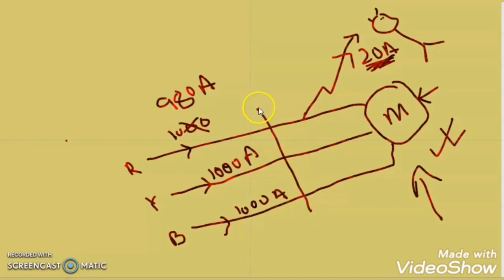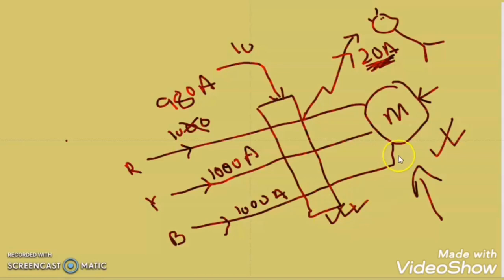As the main purpose of the ELR is to protect the human from this leakage current, the earth leakage relay should trip the circuit at a very minute amount of earth leakage current, though the rating of the load is very high. It means that the earth leakage relay does not care how much current is taken by the load. The earth leakage relay cares how much leakage current is flowing at the earth leakage fault condition. So it will trip the circuit in order to protect the human. I hope you got this.